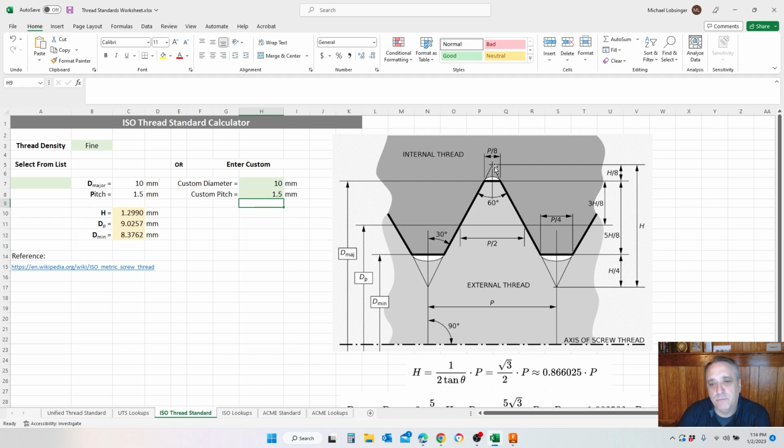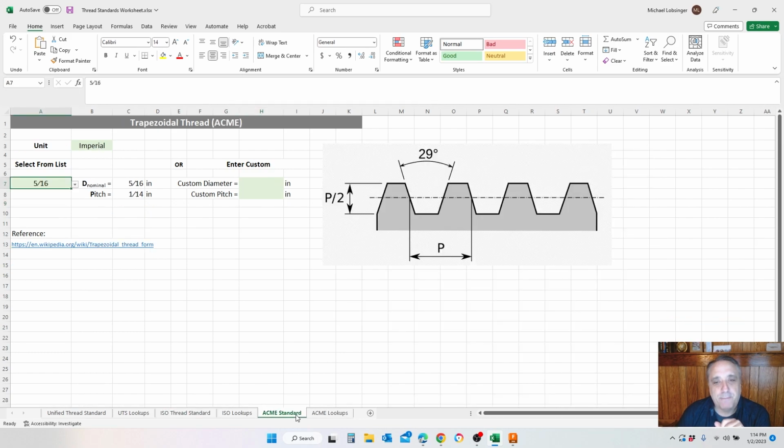So when we do Acme threads, it's going to be a little bit different, which we'll talk about in just a second, of creating your own custom pattern for threads. And that is the case with the trapezoidal Acme type threads. The unfortunate thing is in Acme, it's a 29-degree angle, and you cannot do that in Fusion. That would be a great addition for them, for you to add your own profiles for the coil versus just using theirs. So the alternative is to do 2 steps. We're going to do a coil and then sweep a profile.